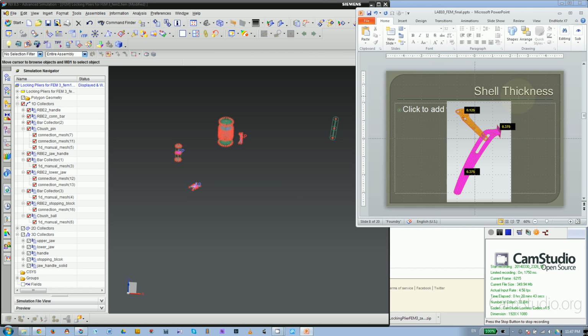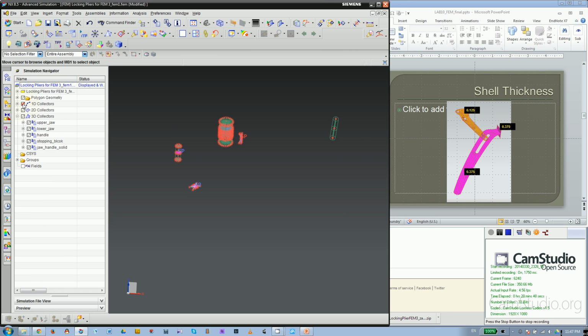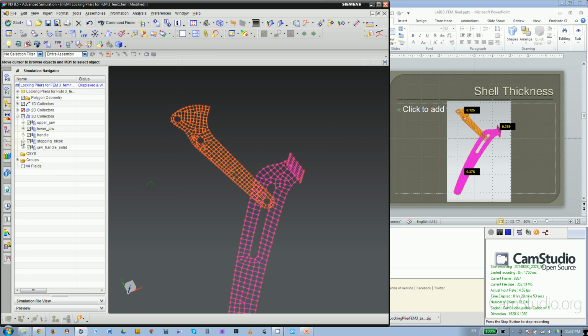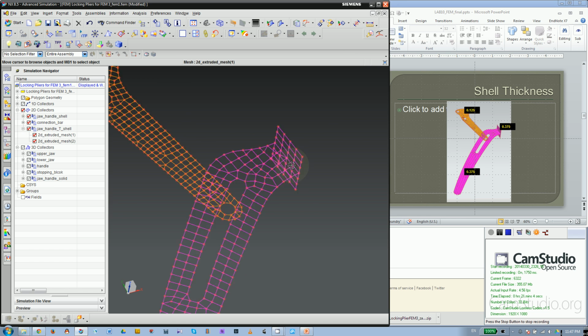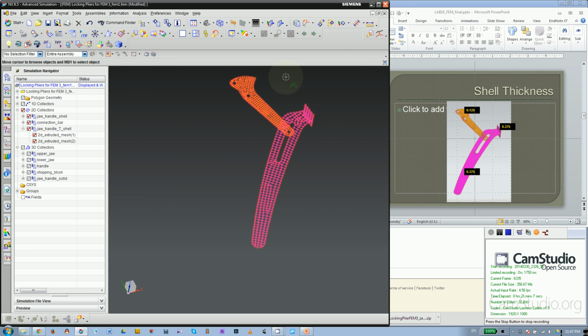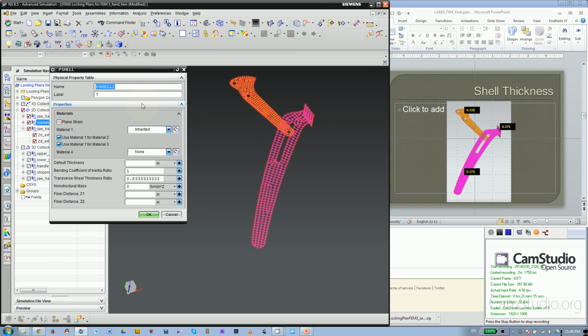Then next, the thickness for the shell. Okay. And yes, in the model, it doesn't have thickness for the shell yet. Okay. Alright, so we have 3 pieces of, technically 4 pieces of shell. Okay, we do have 2 pieces here, extruded from this edge. Okay, and for the connection bar, let's right click, edit, monkey wrench. Material will be steel, thickness 1/8.